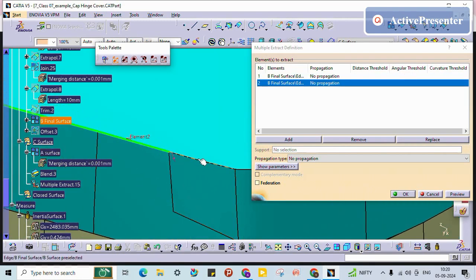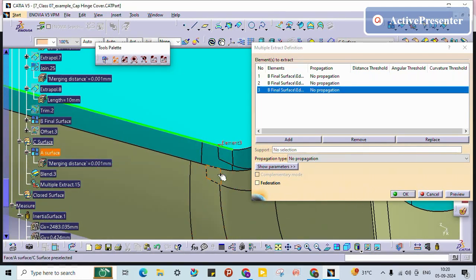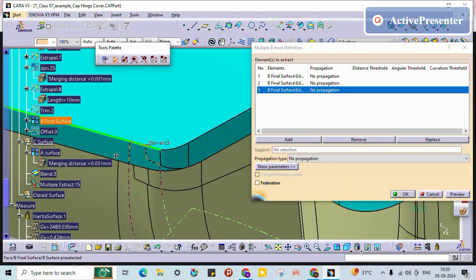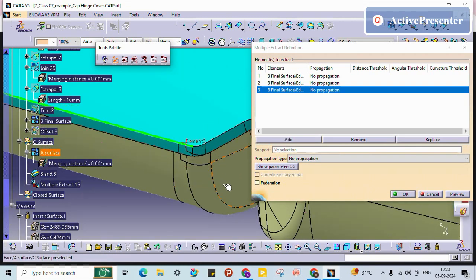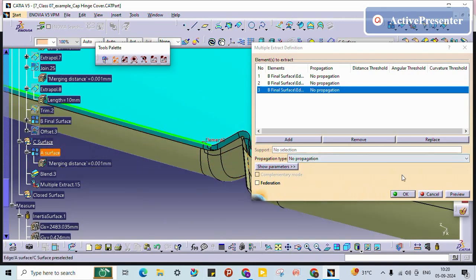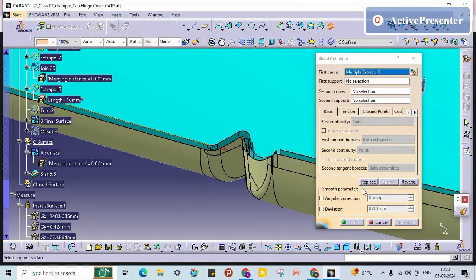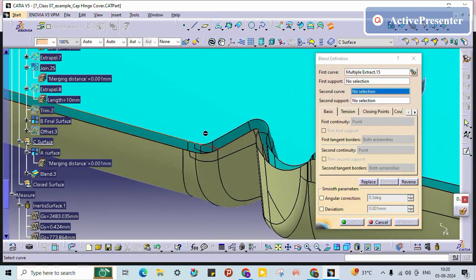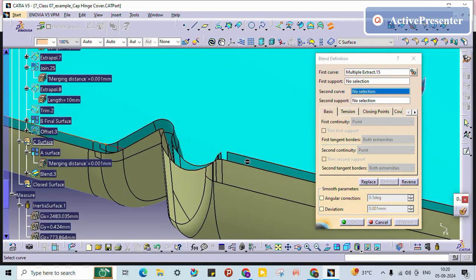So if you have any curved profile, stop before the end, so that it will be created easily. If you keep on giving all the surfaces, definitely the complexity will increase for the profile creation. If you view it continuously, it won't come properly.